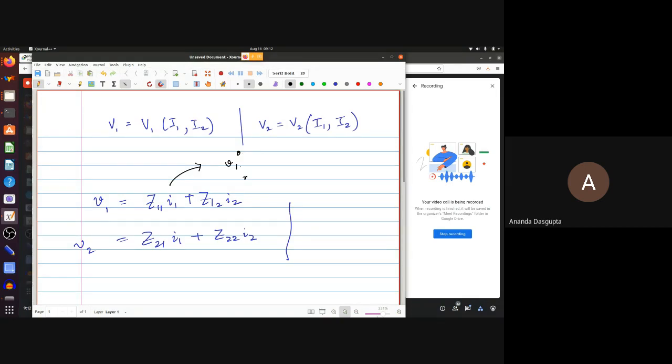So this is going to be V1. Of course, this is really not the voltage. It's a variation of the voltage that we are talking about here. But we will essentially adopt this picture. We will say there is a bias, some kind of voltage and current set up in the circuit, which is the so-called quiescent point, and then we have fluctuations over that. When we say we are dealing with the AC model, we essentially ignore the quiescent point value and look at what happens beyond that. So small v, if you want to implement this particular equation, you say V1 is a sum of two voltages. Because it's a sum of two voltages, it has to be a series.